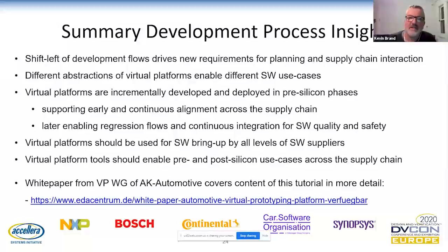Yeah, just to add to that a little bit, especially in the more hardware-dependent software, as you say, and in the controller domain as well. Timing in AUTOSAR is all about timing. And in the likes of an xEV, electric vehicle kind of domain as well, some of the timing requirements can actually be quite strict. You have very small task sizes for a lot of these deeply embedded controller mechanisms. So certainly very different from something at the application level.